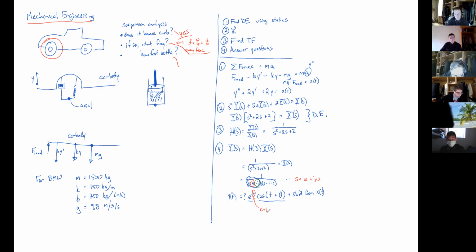And so you know that it takes about how many time constants for a system to settle? Does anyone remember way back from circuits 2? You can see right from here in one time constant, it'll settle out to about e to the minus 1, right? When t is 1.